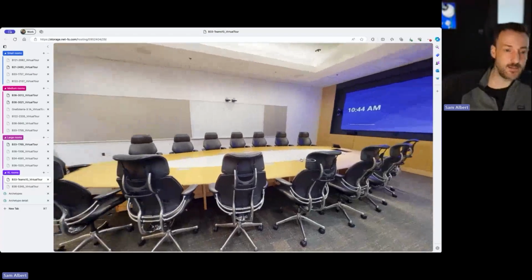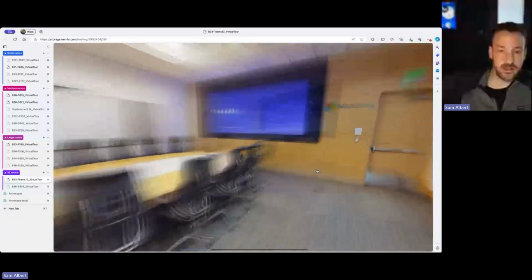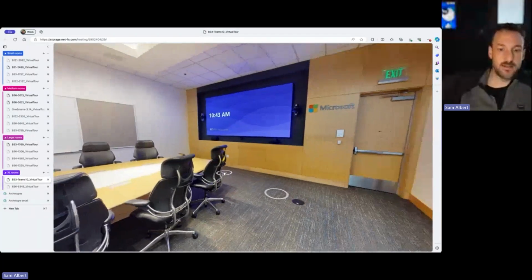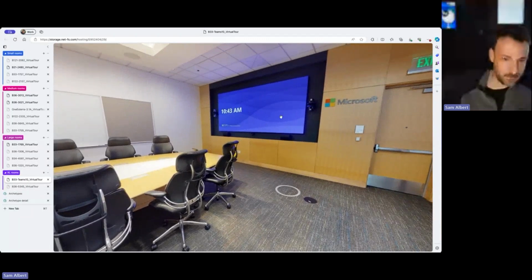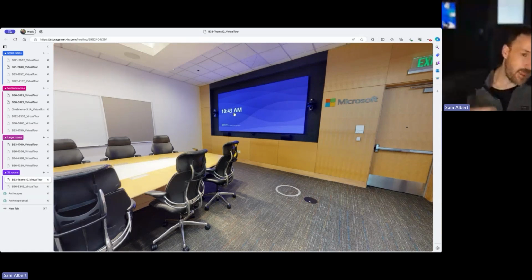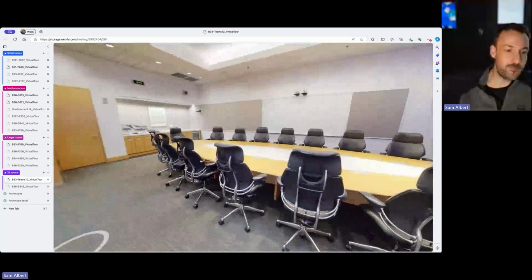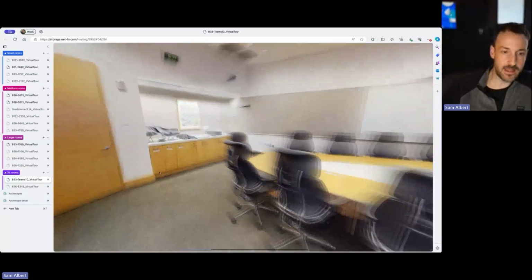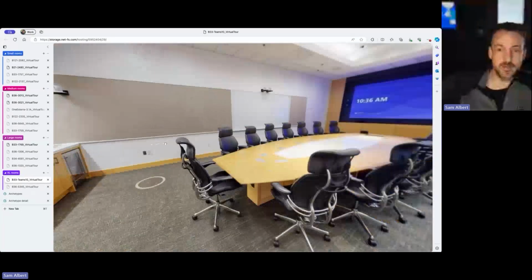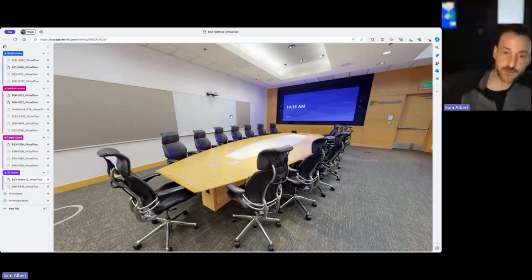The last room that I'll focus on here and spend just a moment on is this LED video wall solution. And this is another, again, beautiful solution. Because they come in panels, there's a lot of flexibility in terms of making this screen fit exactly to the specifications of your room. So this is approximately about a 12 to 13 foot wide display. We're not quite 21:9 aspect. Again, just given the panel sizes, I think we're roughly about 20:9 aspect ratio if we're being specific. But because of the way Teams is designed, as long as we're mapping the right resolution and aspect ratio, the Teams experience looks great on a screen of this size.